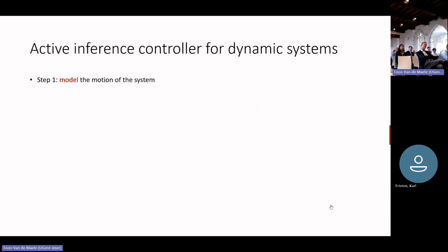There are different methods in system identification, like subspace methods and prediction error maximization. There's DEM from free energy principle as well. So what I would recommend is you can always approximate a very highly nonlinear system. You just imagine that it is going to be a standard LTI system, and then do the system identification on that, get these ABC values, and then you need not do the first few parts. You can just cut that off and then start from discretizing that system.